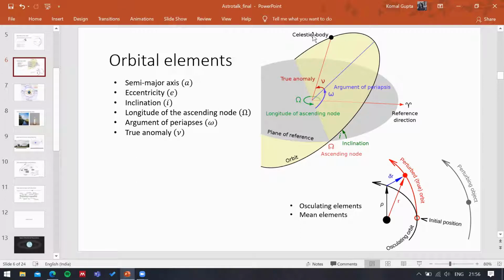If you go to the moon, you will take something else as the reference direction. It could be parallel to the vernal equinox, or it could be something else. But you will need a reference direction to define the longitude of ascending node and other angles. I'm not sure what it is, but this reference direction is the vernal equinox when we're talking about orbits around the Earth. Does that make sense?